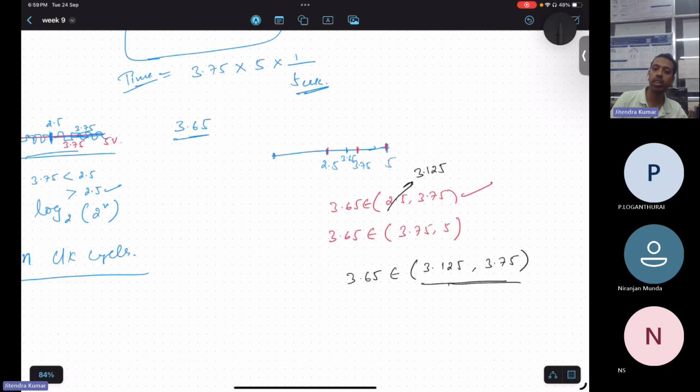And the fastest one is which ADC? That is flash ADC. But there, as many bits as we need, that many comparators we have to use. So in flash ADC, it becomes expensive compared to all the ADCs, right? So that is one drawback.